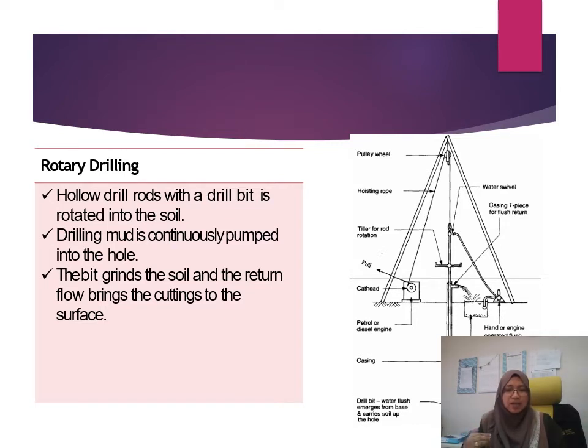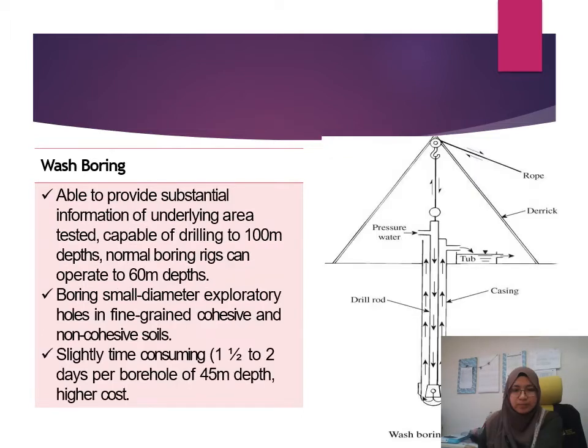Okay, if the size is small, it means the depth of the borehole is not too deep from the ground surface. But if the size of the equipment is big, it can go up to 50 meter from the ground surface. Okay, next is using wash boring.